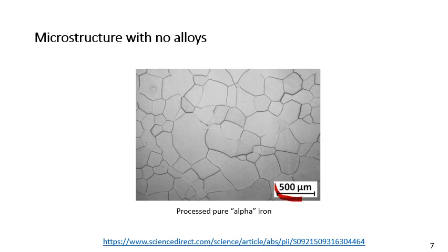This scale bar is 0.5 millimeter, so some of these grains would be almost visible, if not visible, with the naked eye. This would be a very weak product. You would not want to make a pressure holding product like a line pipe out of steel with this microstructure.